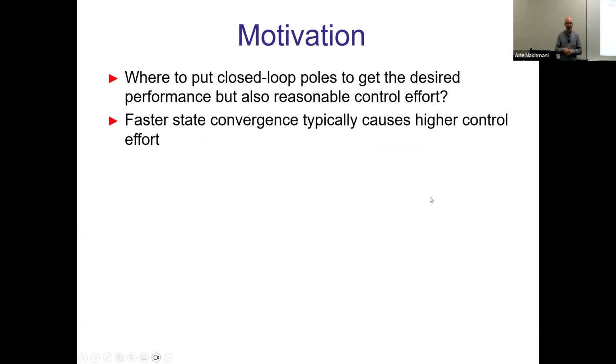So here's our motivation for doing optimal controls. So why not just choose a particular closed loop, where it will have particular performance, it will have particular location in stable location within the unit circle for discrete time or in the left semiplane for continuous time. So why not just choose the poles, to design the controller, practically done, right? We've seen that before. It's not a big deal. It's easy. We have even 3 different ways to do that, right?